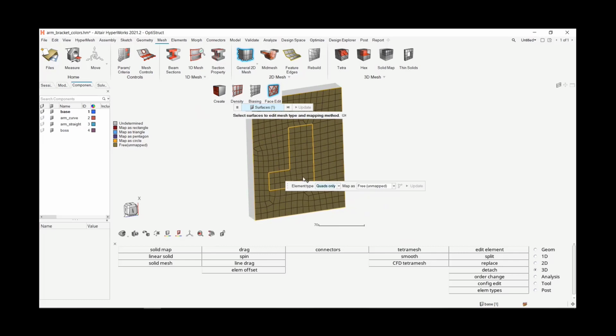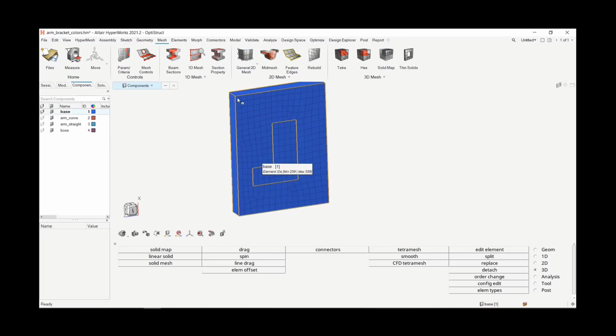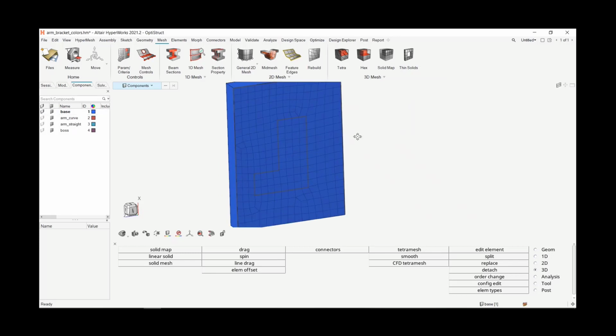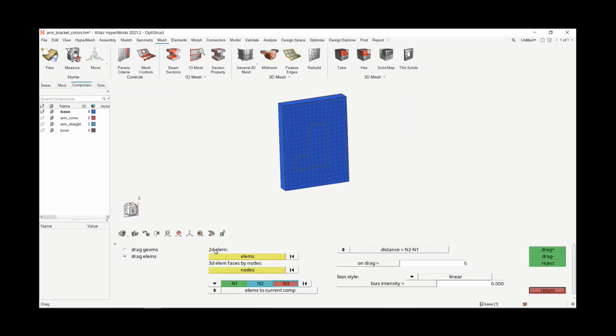That'll be good enough for what we're doing today. One thing to note here is the element density along here. As we're making this, the density and the element spread of these components is going to be important. Once I have this base 2D mesh, if I just want to mesh this component, I can almost just extrude these elements or pull them back, drag them backward. It's not that there's only one tool to do all of these. In some cases, I'll just choose, for instance, in this case, drag, but there are other options here that would have accomplished the task equally as well.